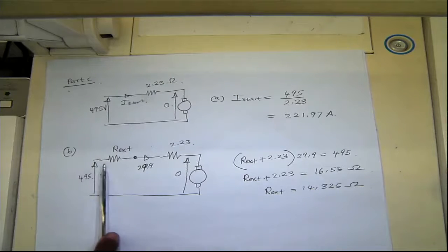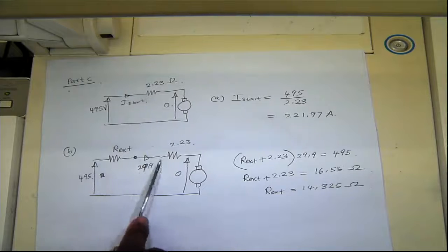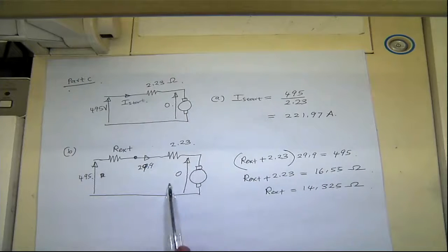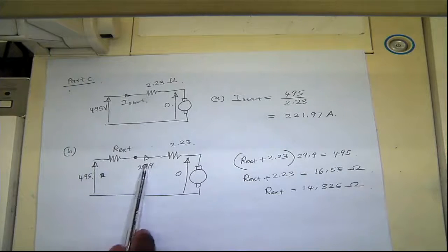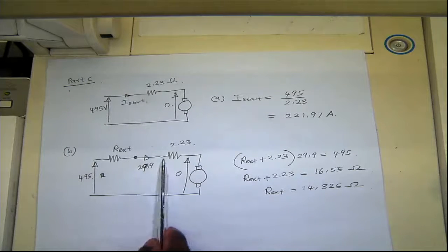Once you apply this voltage across this, you'll have rated current, and then you'll have the rated torque being produced. So it will start up, and then at some speed the voltage drop across these two will be large, and the motor won't be able to speed up to the speed you want.